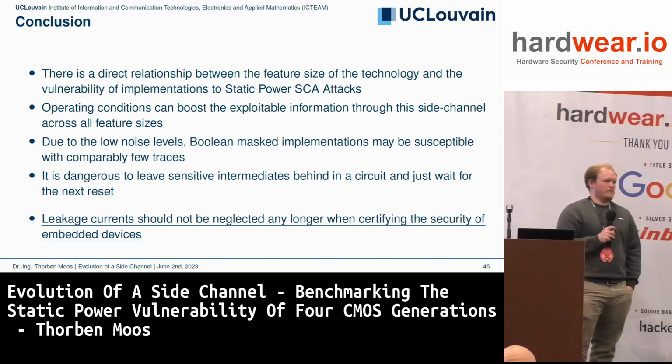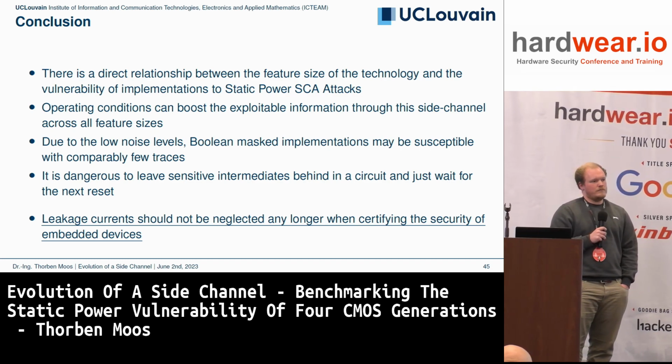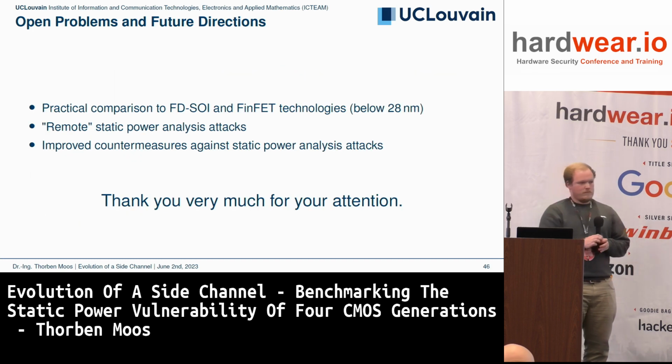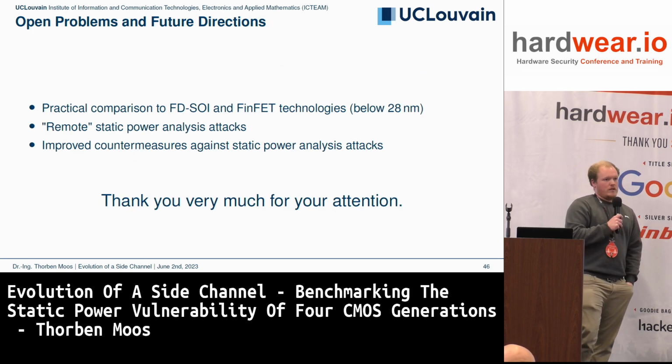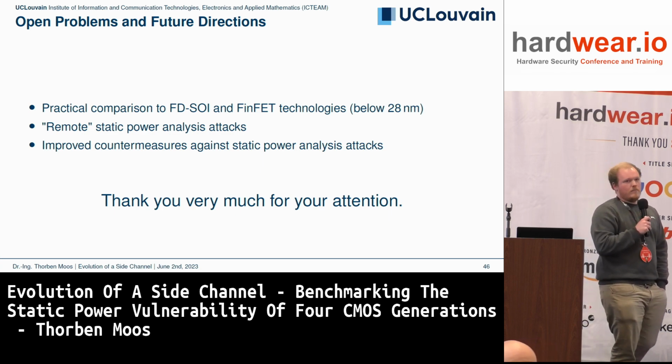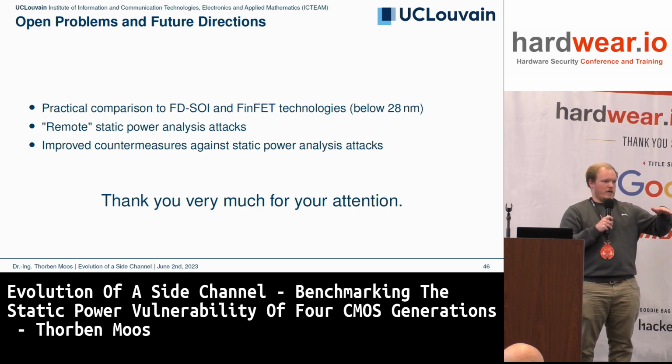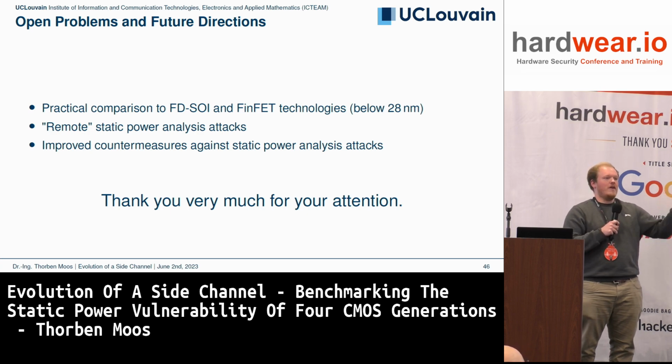Hi, thank you for the nice talk. The 28 nanometer was FDSOI or bulk? It was bulk CMOS. So if you use FDSOI, then you are in a better position to control the static leakage. Yeah. I mean, you have this bump when going first from bulk CMOS to FDSOI or FinFET, where the leakage currents don't increase at this level. But then if you compare multiple FDSOI technologies, it still increases. I mean, it's not immune to static power. We would wish it would be, but it isn't.